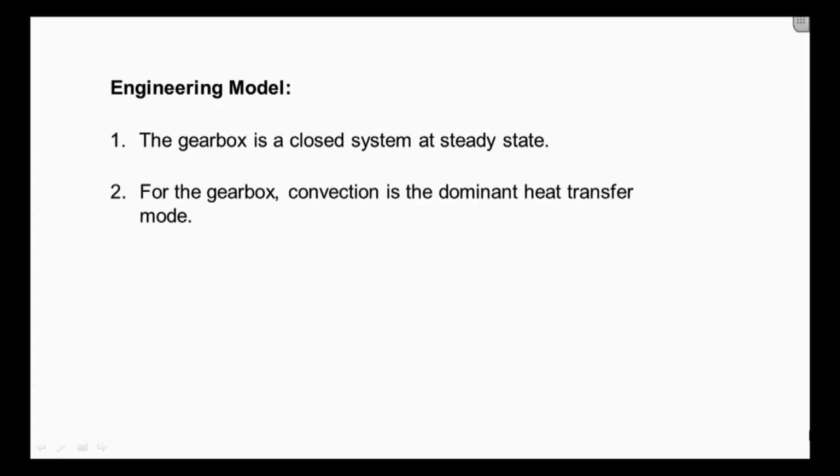The next step is to develop an engineering model. In other words, listing a set of simplifying assumptions which will allow us to perform the analysis of the problem. The gearbox is a closed system at steady state, and for the gearbox, convection is the dominant heat transfer mode.